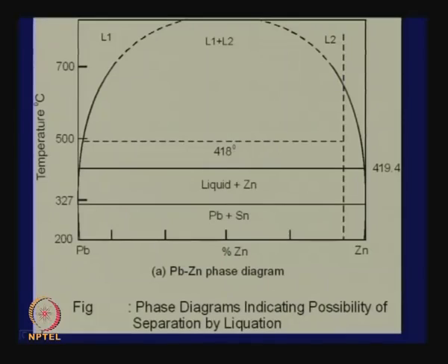from the liquid state. It is a very interesting device that captures the zinc vapors in molten lead by spraying molten lead on the zinc vapors, and you get the zinc lead alloy. Then that is cooled down. So, the zinc precipitates out and the lead is still molten, and it is recirculated for spraying. So, that lead zinc system is very important.